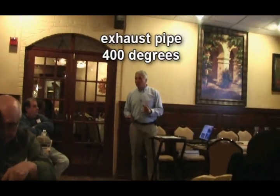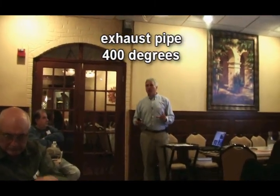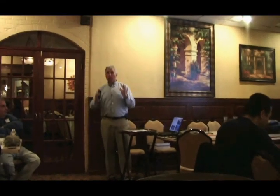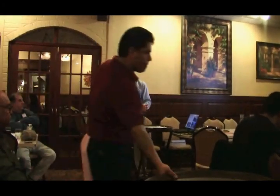Now, you have an exhaust pipe. The typical temperature of an exhaust pipe for a generator set is 400 degrees. Now, we have a 400 degree pipe going through a wall, which is not different than when you put a freestanding fireplace that you find in a room through the house. It's got to be the same type of thimble. It needs to be an air space between the hot surface and the construction material.